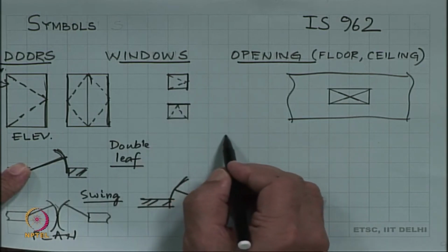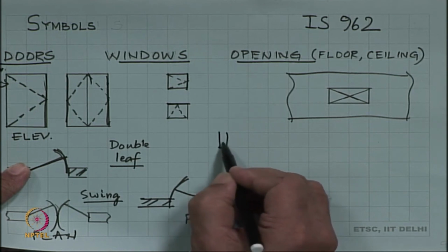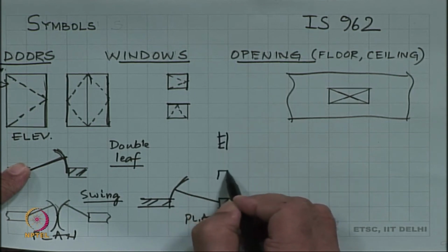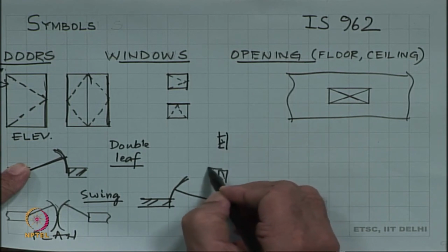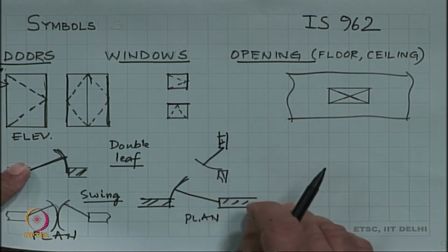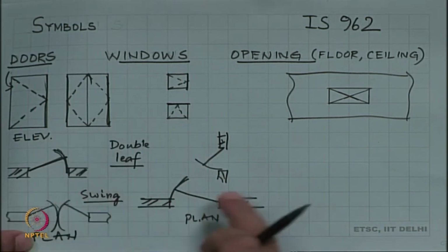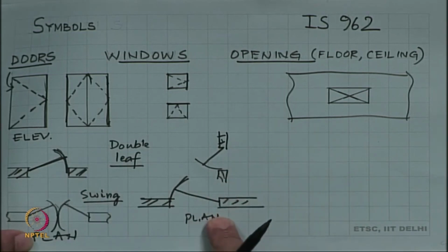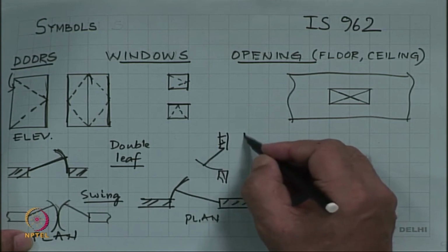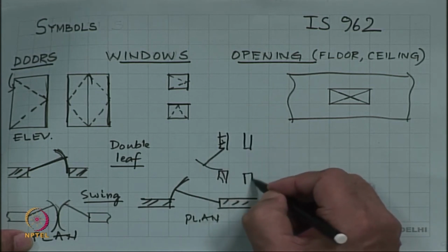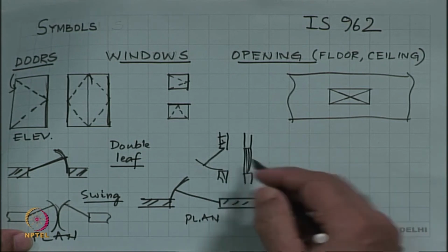So, in this elevation view, this window, this is the wall, this is the wall over here, this window would open like that. So, that is again as before in the elevation view, this would be in the plan view. Or if we do not show this, we can also show it the way we have shown earlier, we just do it and in between we have two small lines which tells you that this is the window.